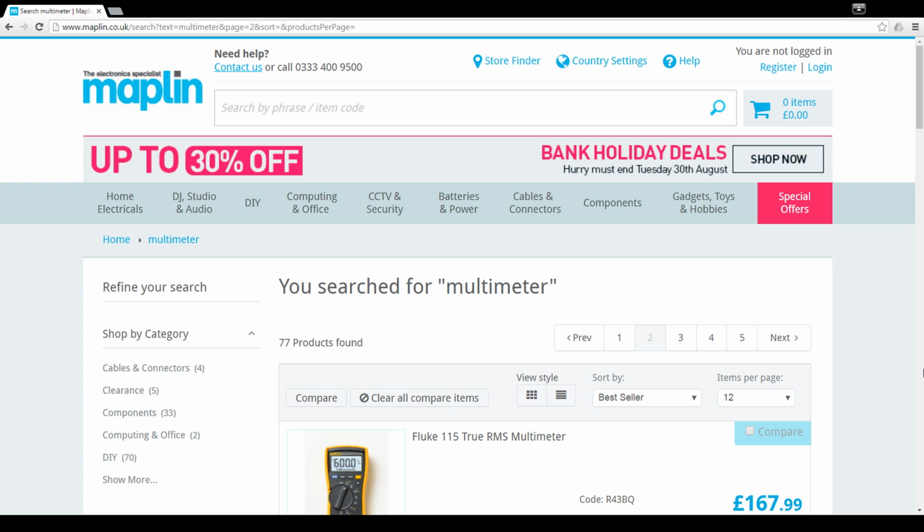But you can get unpolarized electrolytics. They're pretty expensive. They do have higher voltages, but they're normally of lower capacitance values. But they are used in some AC circuits. If you checked out Great Scott's video recently, you can see that inside one of the cases they had a few large capacitors.